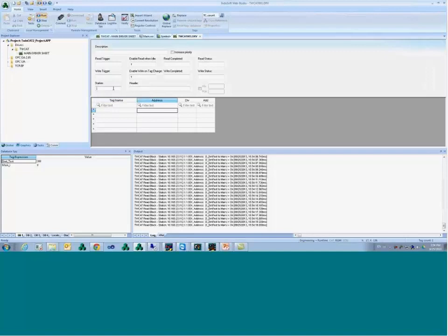Okay? Station. Here I put where is the PLC that I'm going to communicate with. So I'm going to enter here the AMS net ID of that PLC that I'm trying to communicate with. All right, AMS net ID and runtime number. And on the header, I specify that I'm going to communicate with the tag names.